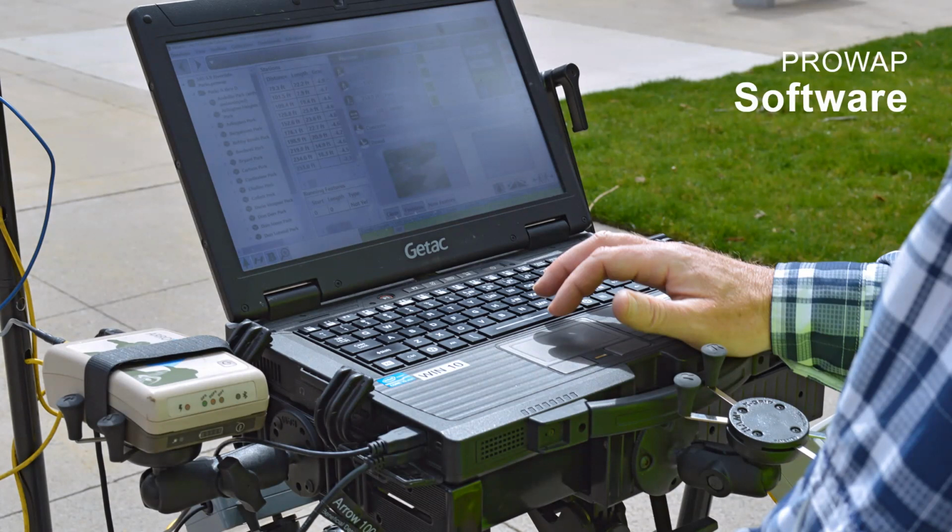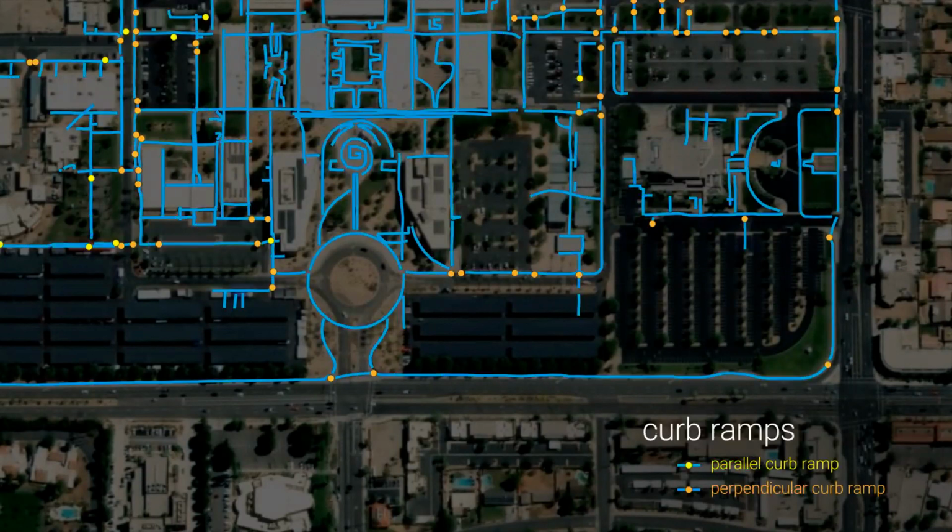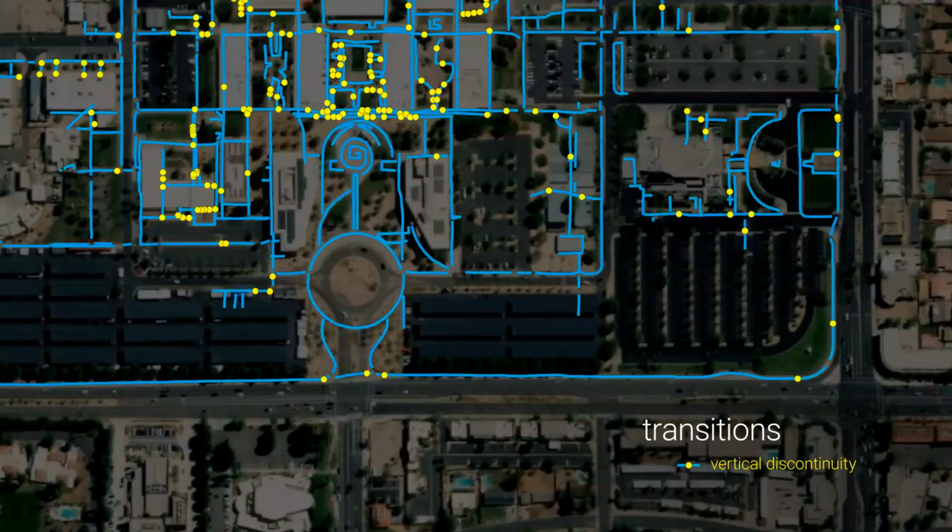A picture is captured at every station along with a GPS point and an information snapshot of the path of travel at that point. The ProApp software further assists the assessor by providing questions, text, and visual guides for all required measurements at elements or issues. Path of travel information is collected in line data, which includes cross slope, grade, and tread width. Point data is also collected for every feature, which can include curb ramps, tripping hazards, pedestrian push buttons, sidewalk furniture, or many other features.